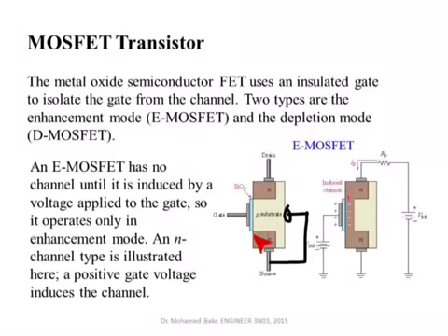There is a layer that exists there because of the doping they create. So they can have some doping here in N-type material, and in that case, it normally conducts current, unless you make the gate too negative relative to the source, and in that case you are repelling these electrons away from this region, and then you are eliminating the conduction channel.